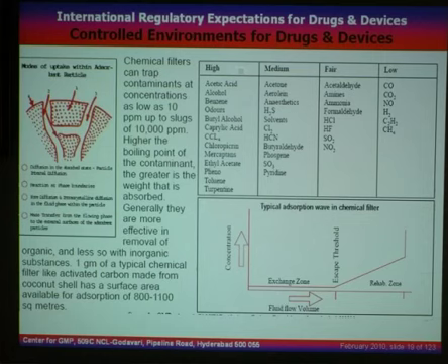Now, there is one more thing you can do. Use activated carbon granules. You put them into a muslin quilt, making little pockets in which these granules sit, and just suspend them in the plant room, in the air handling unit area, so that the air passes through this before it gets into the supply duct. You will find vapors are removed, odors are removed, because 1 cc of activated carbon can absorb 1000 cc of gas.